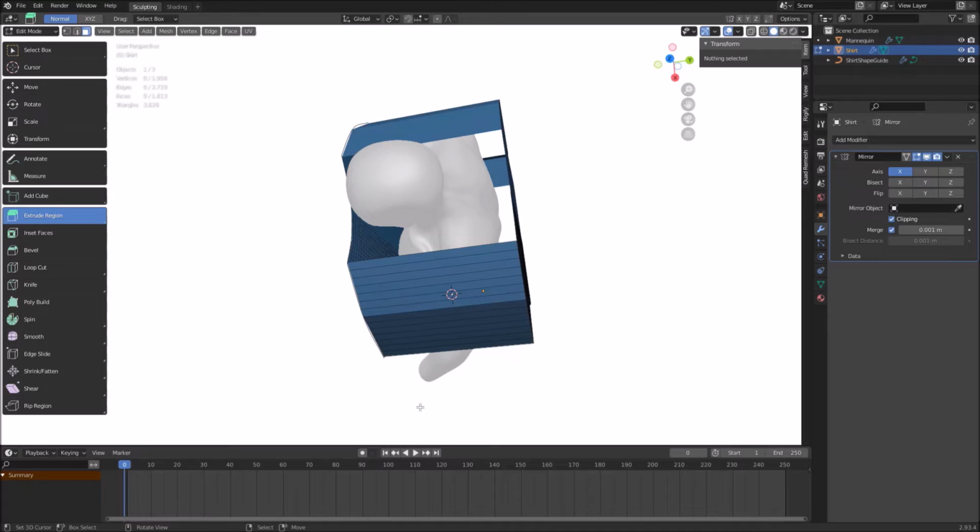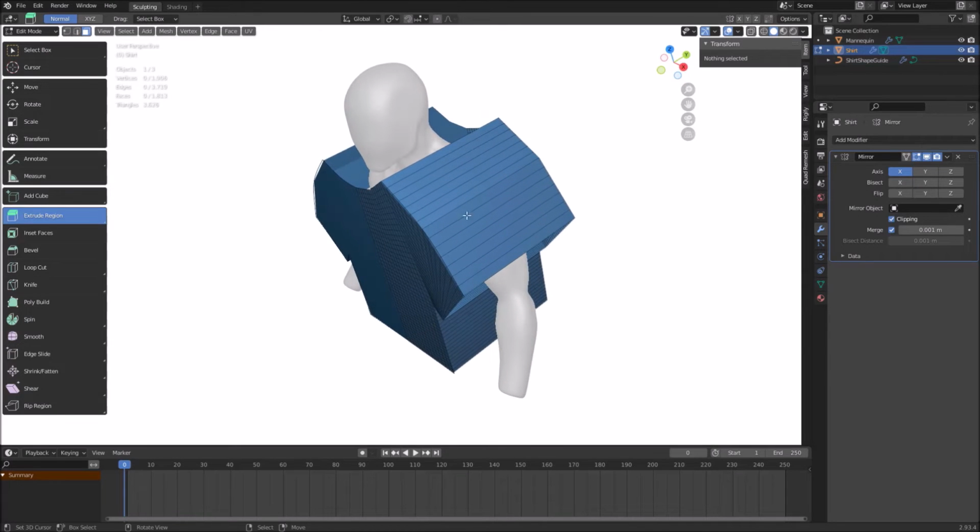We're almost done. We have the holes in the shirt now. However, we don't need these outer perimeter polygons either. These are going to get in the way of the cloth simulation. But instead of completely deleting them, we can actually leave behind the individual edges that run from the front to the back, and we can use those edges to sew the front to the back during the cloth simulation. So we need to delete the faces, but leave behind these edges.